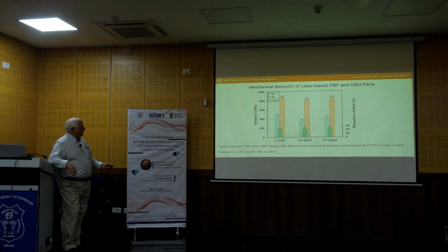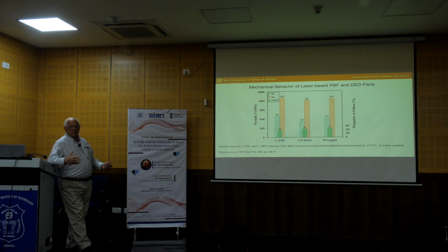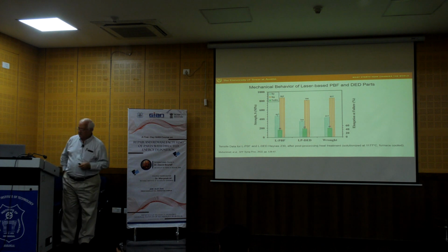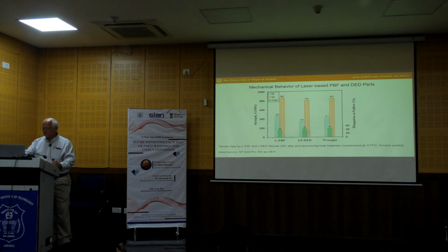The yield strength is down here again. I would say it's completely consistent with the previous plot. The yield strength for the DED material is a little bit lower than the others, but again, I don't put much weight on that because I think statistically that would largely wash out. And then, of course, we have the ductilities as well. So for the powder bed fusion, again, I would say these are all pretty much identical as well. So we were able, again, with the nickel-based alloy to hit the mechanicals just fine.